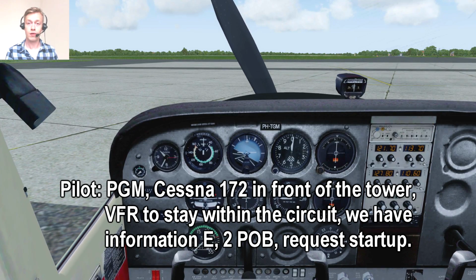Okay, then we're going to say what kind of flight we're going to do. So we're going to do VFR to stay within the circuit. We're going to report that we have information echo received, and we're going to report the amount of persons on board. It's not really necessary per se, but it helps in case of an emergency, ATC to determine how many people are on board, and for the emergency services to respond to that appropriately. So in this case, I am on board, you are on board, so we have 2 persons on board basically, and then we're going to request startup.